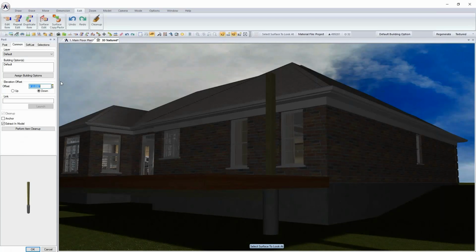Now you're at a bit of a disadvantage because you don't know the site and so on. But basically, I do have a bit of a flat site back here that's about 3 feet below the top of the brick wall, and so if I type in 7 feet down, the default was 4, it's going to drop that sonotube down into the actual grade itself. Okay, and so that's going to push that down.